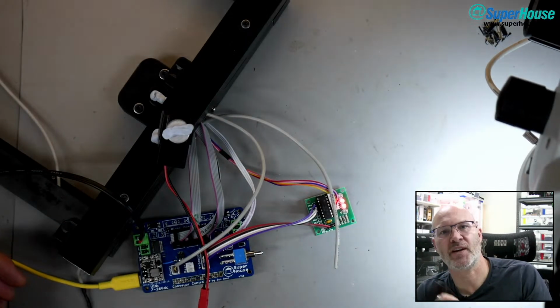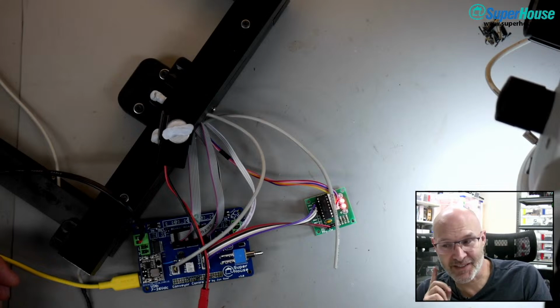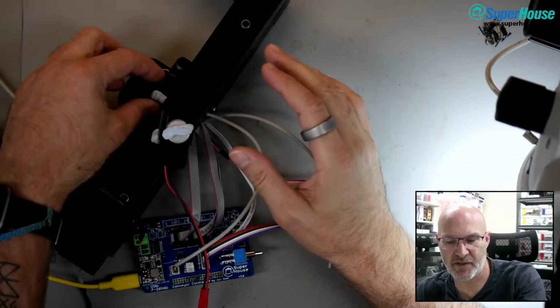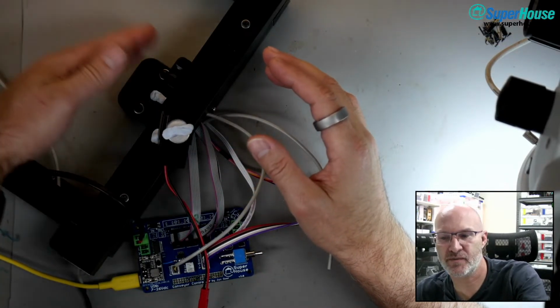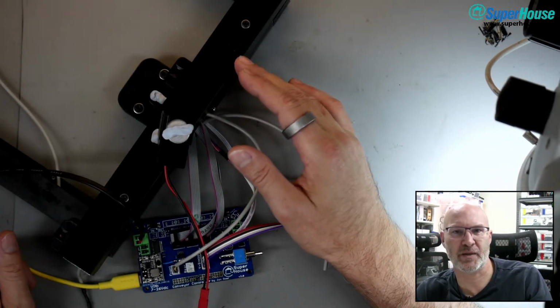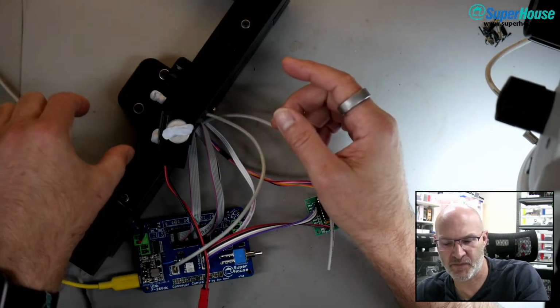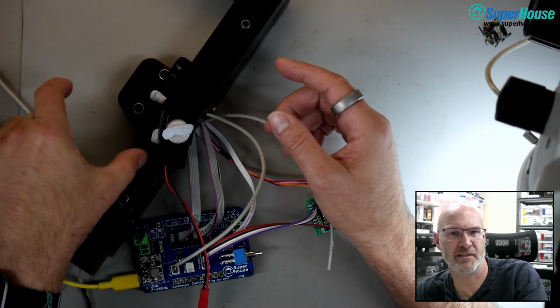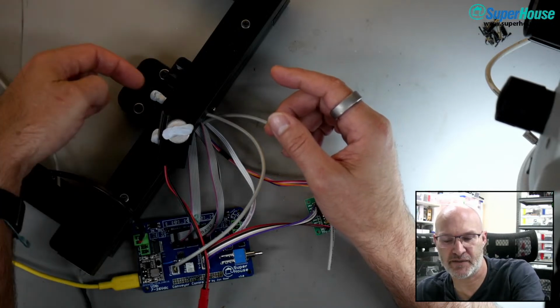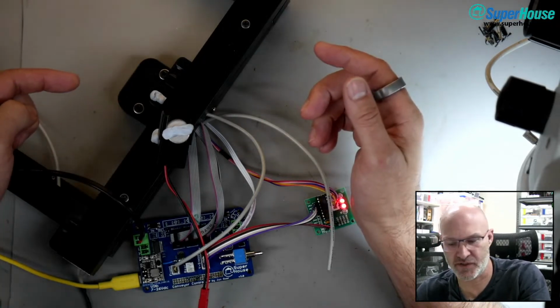But as long as it keeps track of the target position, it doesn't forget it, and you don't miss steps, so the stepper never actually skips, it should be able to go to a known position and not overshoot and close too far, because I've got that 45mm limit. If you ask it to do anything less than 45mm, it'll just refuse to do it.